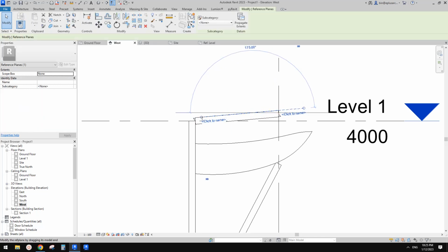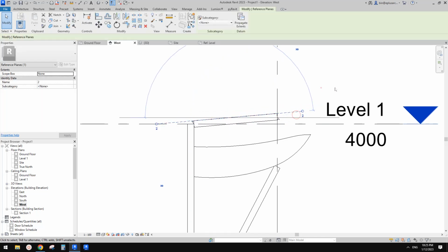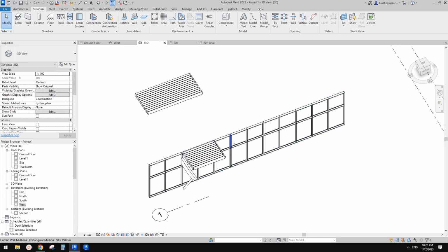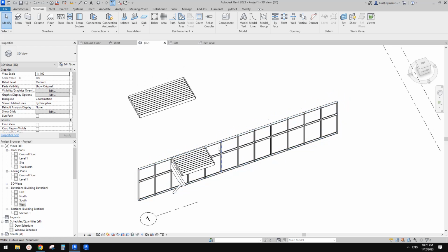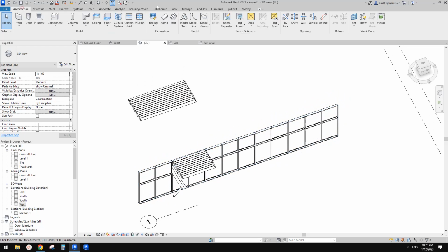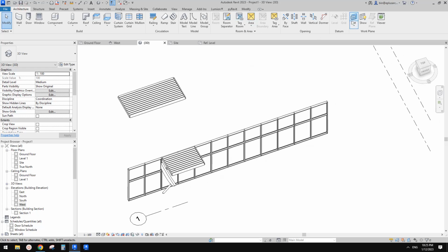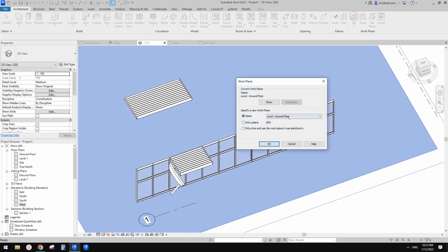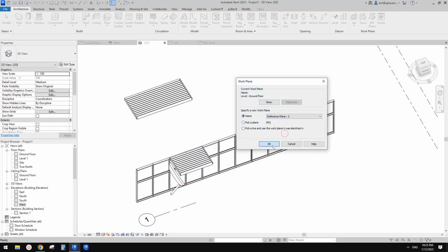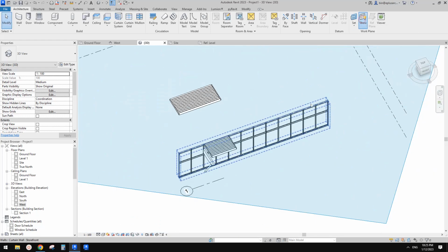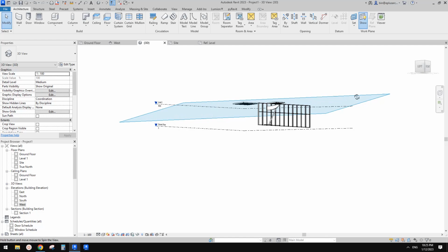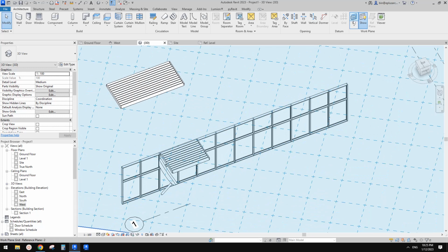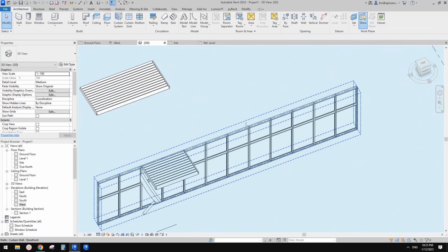So this is a reference plane, another reference plane. I'll just name it 2. Okay, so go to 3D view, and this reference plane, of course, is invisible in 3D view, but it's there. Okay, so for example, you can see them if you set the work plane onto that reference plane 2, and with this show work plane, you can roughly get some idea where that work plane is. Okay, so now I have set the work plane onto that reference plane 2.